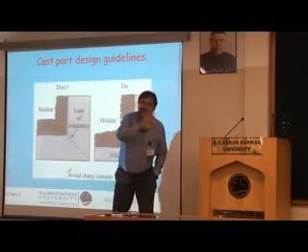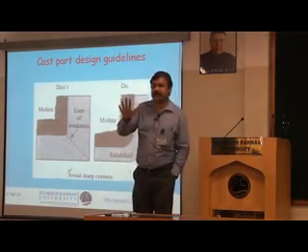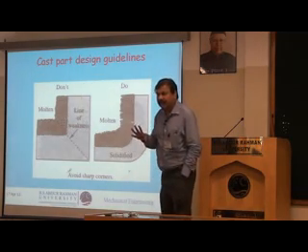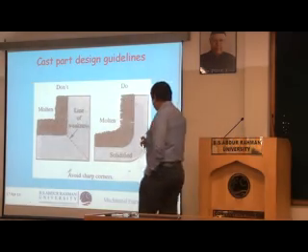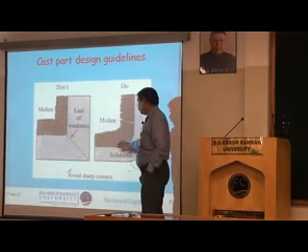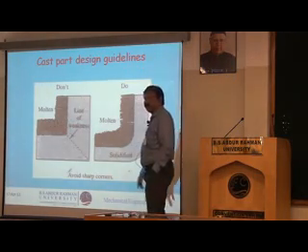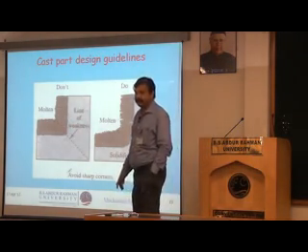The idea is you should ensure uniform solidification. To have uniform solidification, what should we have? You should have uniform thickness. So I should have a uniform thickness so that solidification takes place simultaneously.